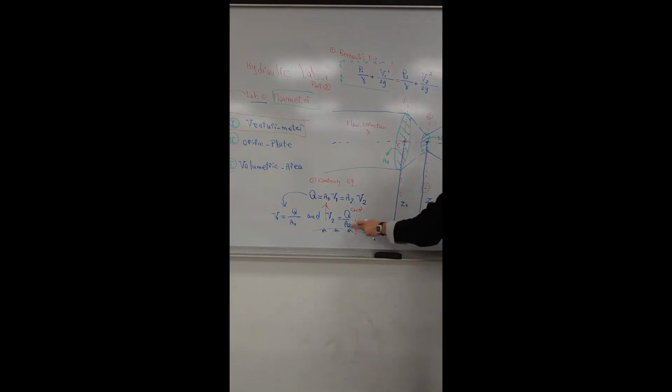As we see here in cross-sectional area 2, area drops, hence velocity increases. So the whole term should be equal to the first part. As velocity increases, something should decrease to compensate. Gamma and g are constant, so pressure in cross-sectional area 2 drops.